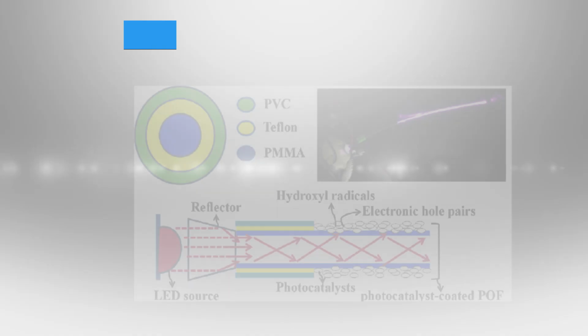One important thing to mention here is that in all three types of fiber, namely step index multimode, step index single mode and graded index multimode, the thickness of cladding material around the fiber core should be at least several wavelengths. This arrangement will prevent light energy losses due to absorption and scattering.